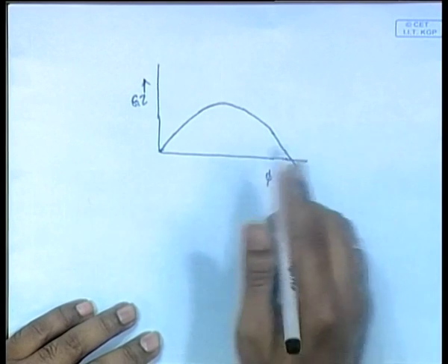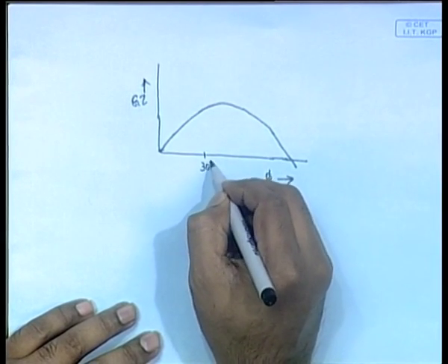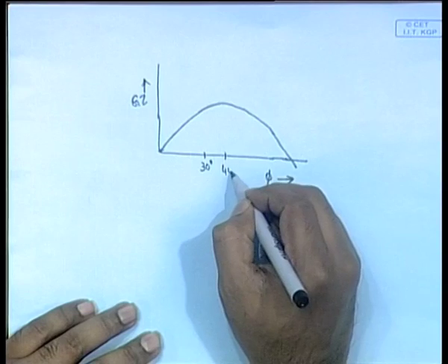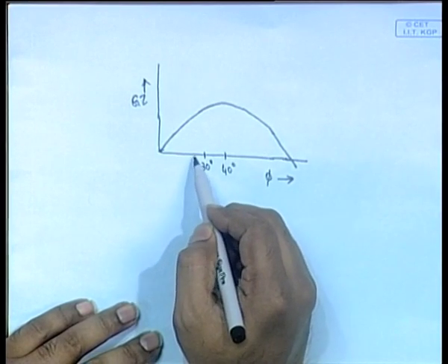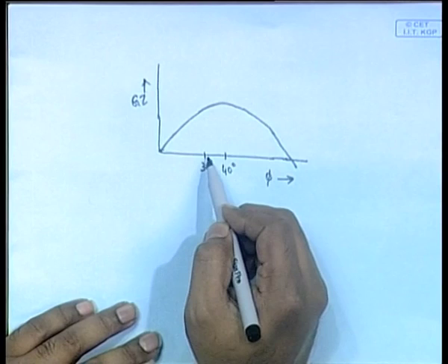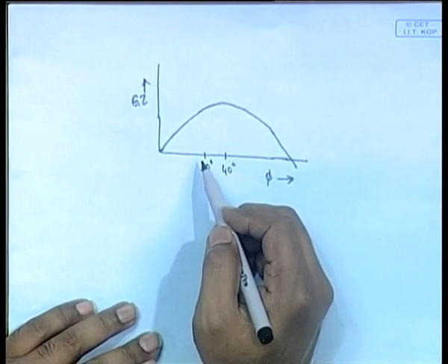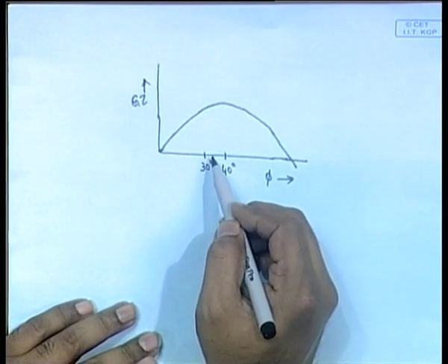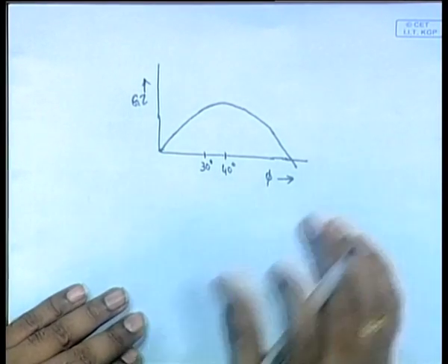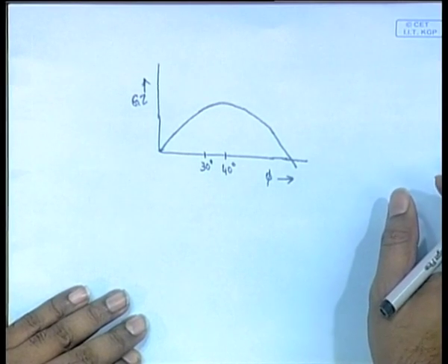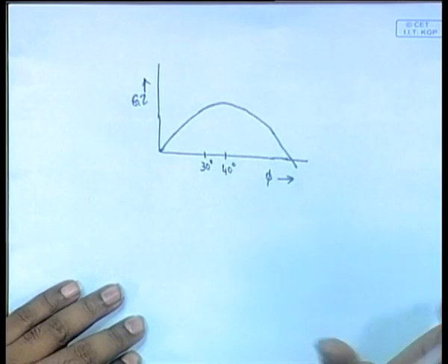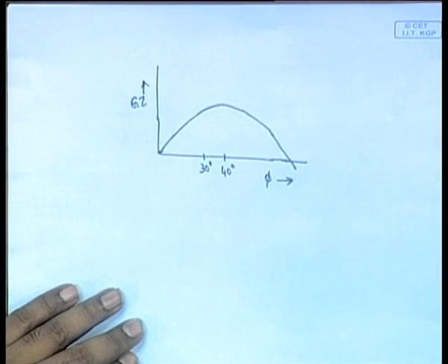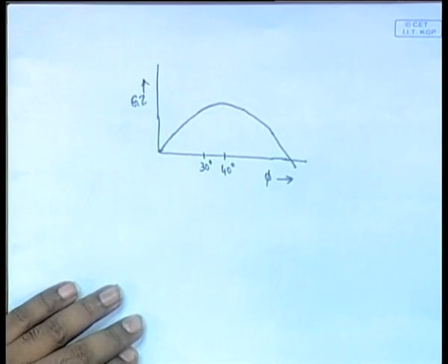We have already seen how the rules exist, which state that the area under the statical stability curve should be greater than 0.055 meter radians between 0 to 30, 0.03 between 30 to 40, like that we described the rules yesterday. So, these are the basic set of rules around which the stability calculations and stability check is usually done by the classification societies like Lloyd's Register or the American Bureau of Shipping.